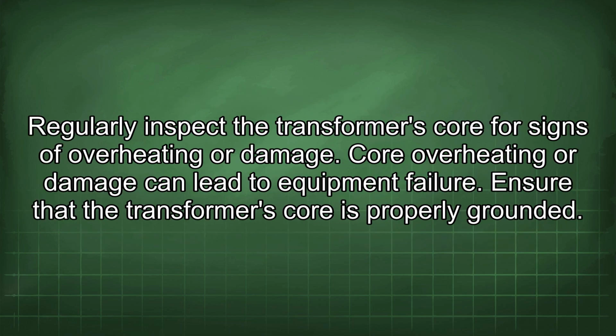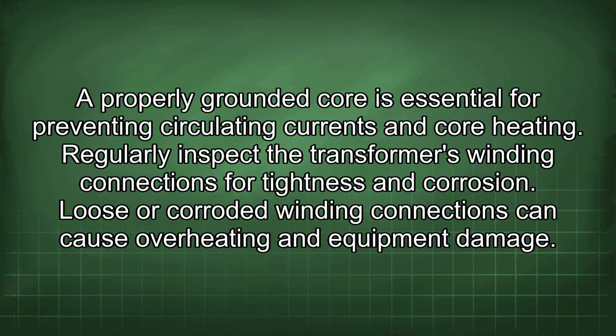Regularly inspect the transformer's core for signs of overheating or damage. Core overheating or damage can lead to equipment failure. Ensure that the transformer's core is properly grounded. A properly grounded core is essential for preventing circulating currents and core heating.